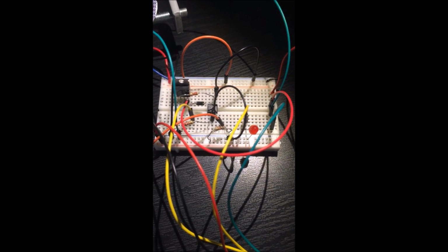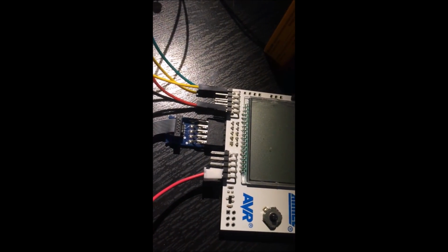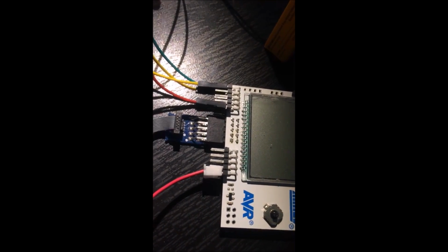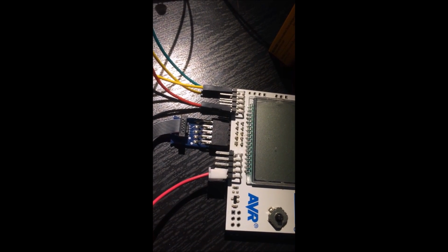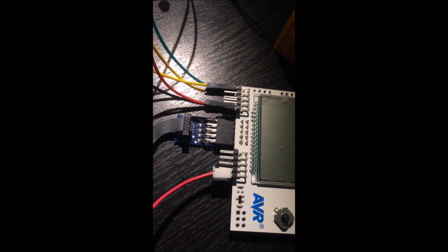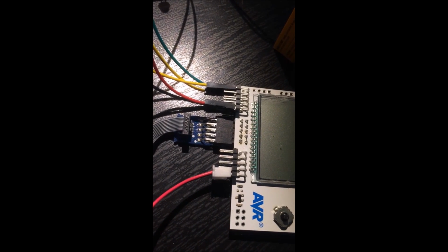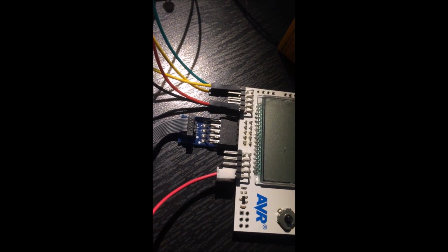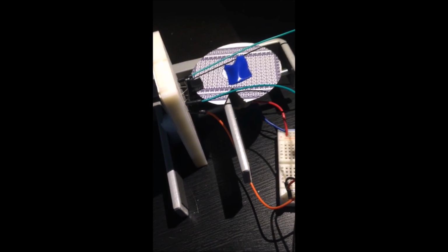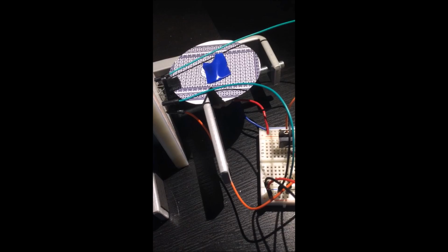Here we have the DC motor control circuit, just like the previous labs, and the opto interrupter is also hooked up to the Butterfly. Port B pin 0 is connected to the interrupter and is an input. Port B pin 1 is an output that goes to the DC motor, and port B pin 2 just goes to this little status LED that lets me know every time the slit passes through the interrupter.